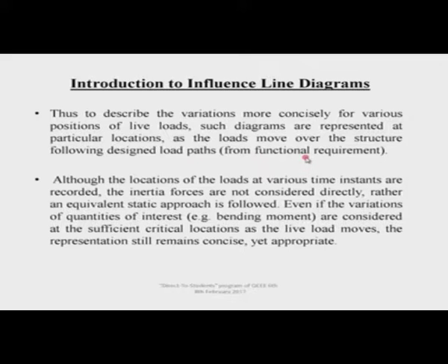Designated load paths mean, for bridges, that a railway line is laid. Even for road bridges, the lane is laid where the heavy trucks will ply. Also in industrial cranes, you know where the load is hung and how it is moved.